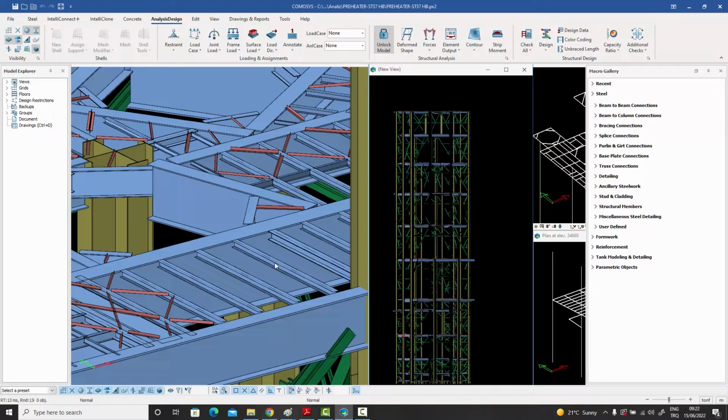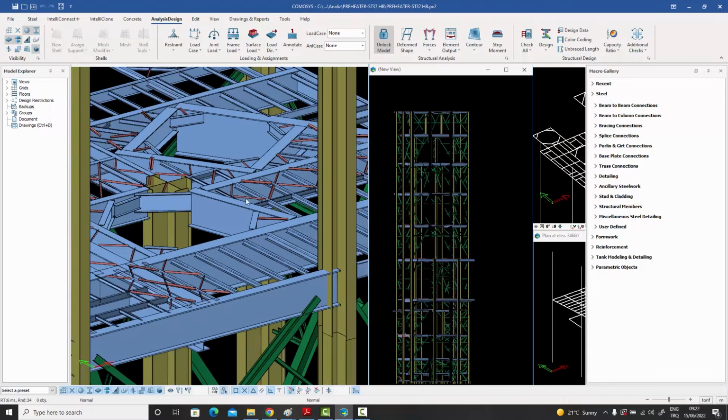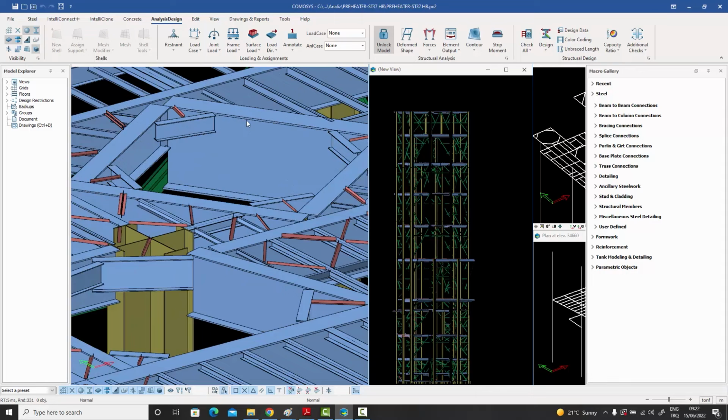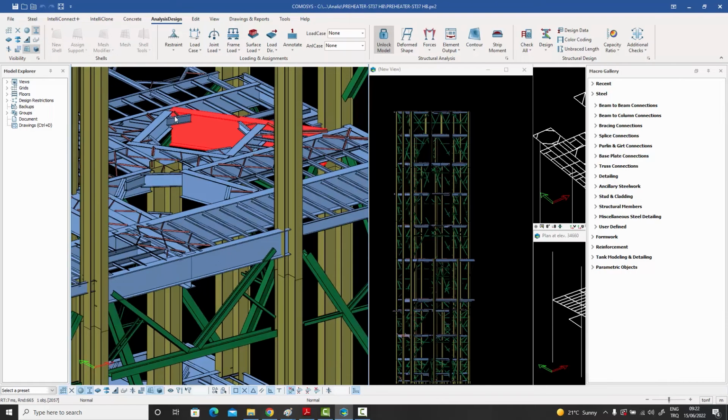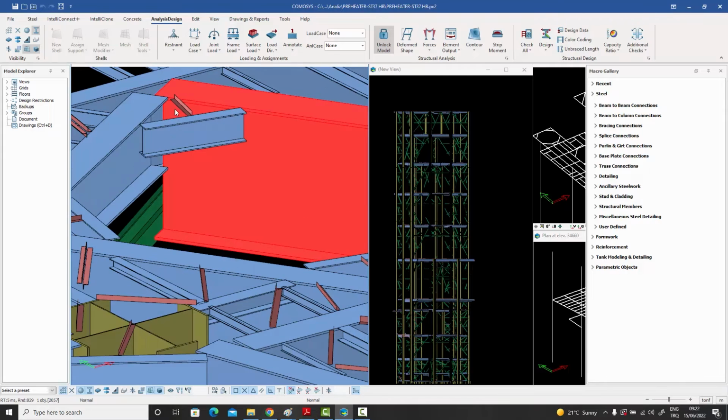But the point being that these are not designed to capacity, because if they're designed to capacity, you will get an unnecessarily high number of bolts or very, very thick plates or very large weld sizes, which is not practical. And the reason for that is that the realistic forces inside them are actually extremely small, in the sense that, for example, a beam as big as this might have a shear force of maybe just say 20 tons at the end of it, and 20 tons, with the kind of bolts that we have these days, would require maybe just 4 bolts.